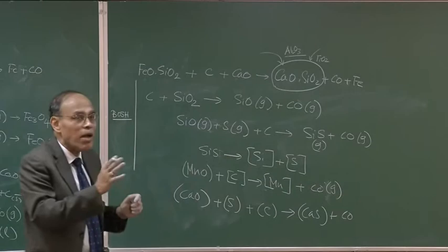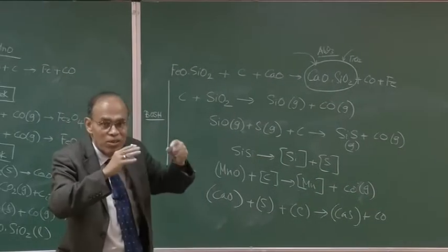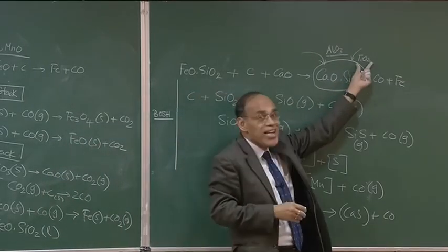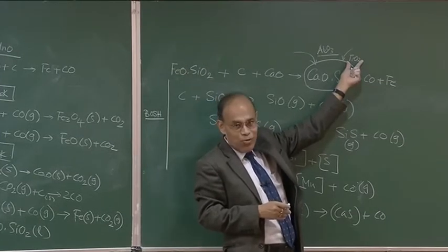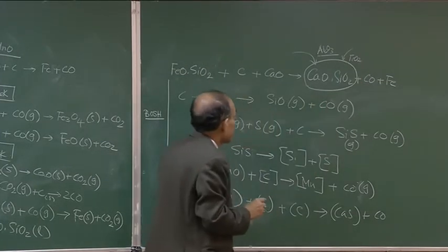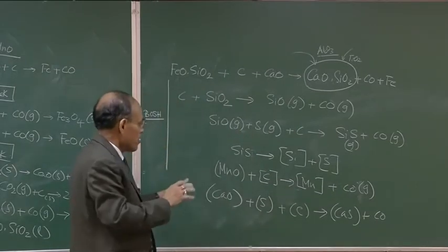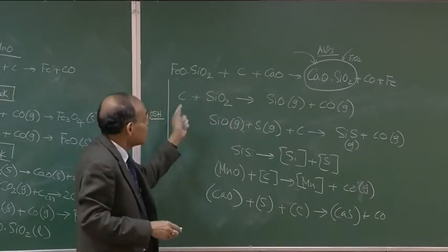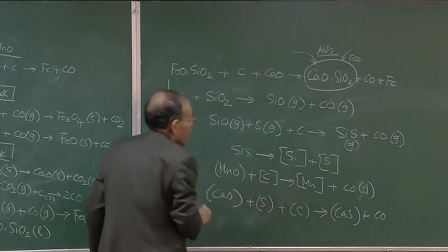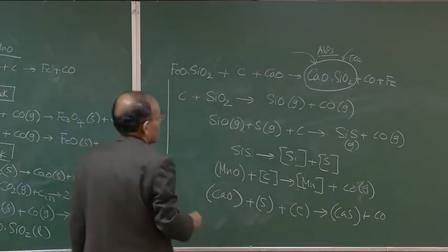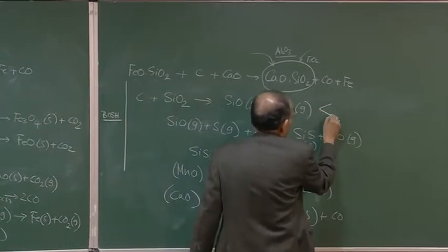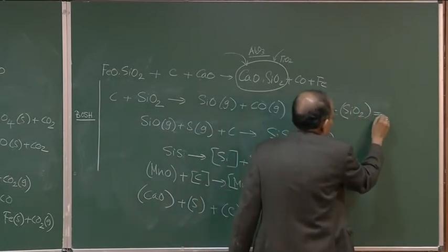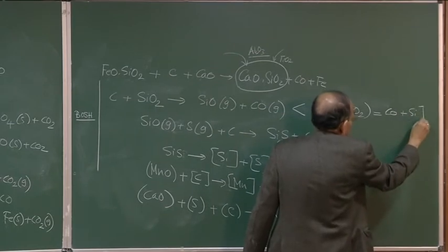They are at very high temperature, very intense carbon monoxide concentration. Only carbon monoxide can reduce titanium dioxide. So titanium oxide as well as silicon dioxide are partially reducible oxides in the blast furnace environment. And then I have shown how the sulfur can get into the slag, how the sulfur can get into the metal, how silicon reduction can take place, and silicon suboxide can form, and from there we can have the reduction reaction, another reaction which could be carbon plus SiO2 equal to carbon monoxide plus Si.